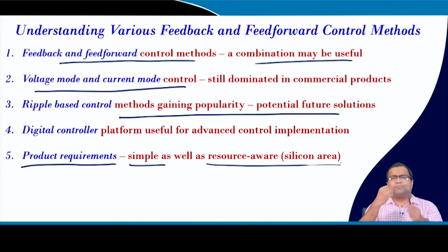But in case of a little bit higher power applications, where we still use bulky off the shelf components, many of these can be combined to make an IC to increase the power density, and that is the future trend. Sometimes people are now talking about integrated magnetics in the PCB itself.